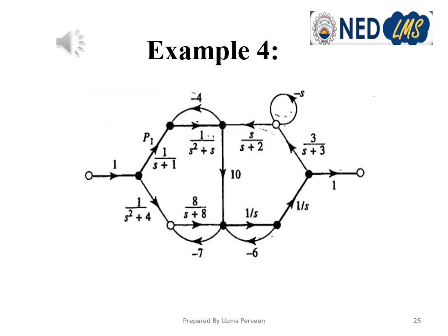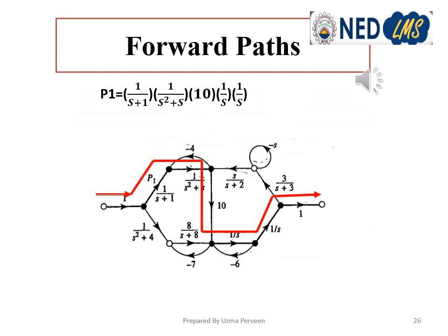Okay, now let's try one more example to find the transfer function, output upon input, in the S domain. Here we have to see carefully the number of forward paths, the number of loops, and the combinations. So we'll first consider this diagram for the number of forward paths.